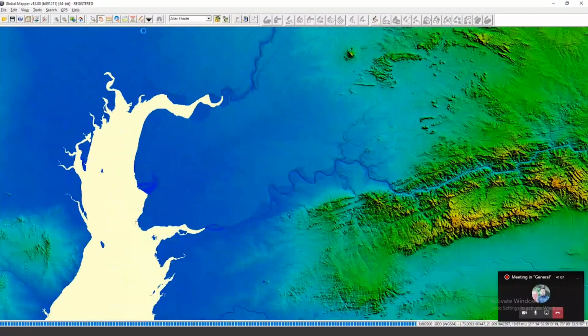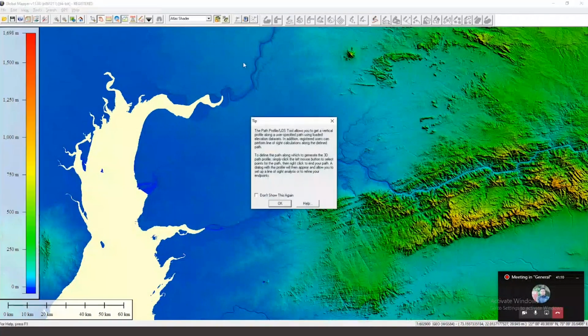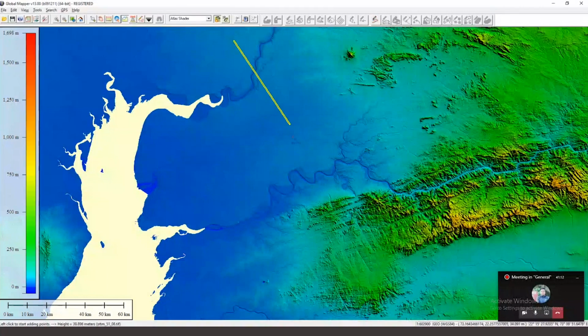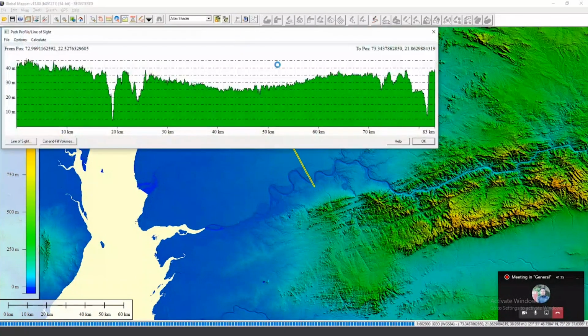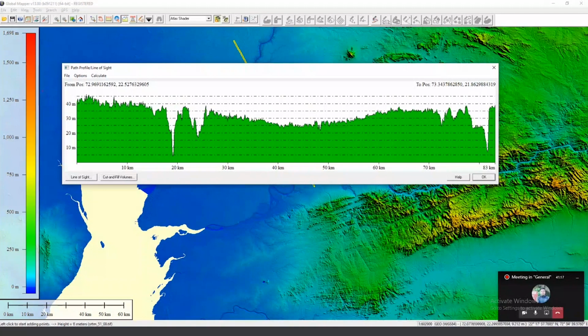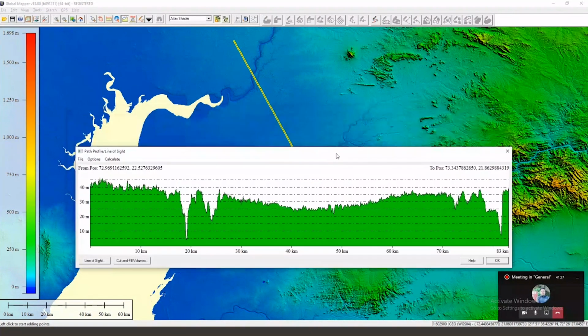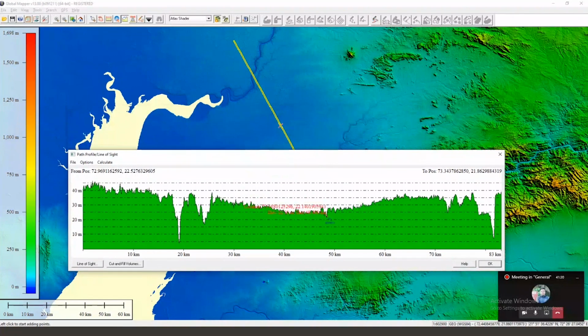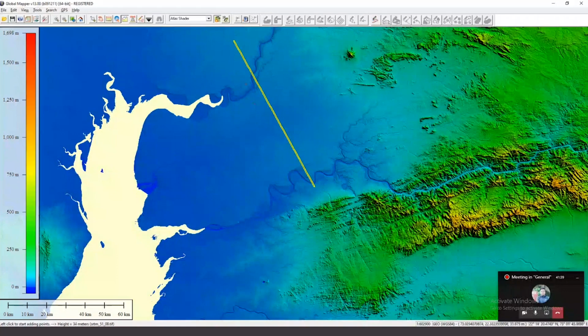And if you see the elevation or the cross section of all these rivers, we can see it is almost flat terrain. The variation of the height is from 40 meters to around 30 meters. This area, around 83 kilometers that you are looking at, has only a 10 meter difference in height. One river comes here, another river comes here, and a third river comes here. So this almost flat land produced by all these rivers together, we call a floodplain.